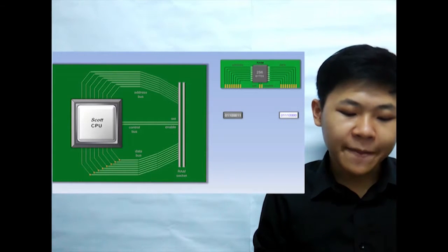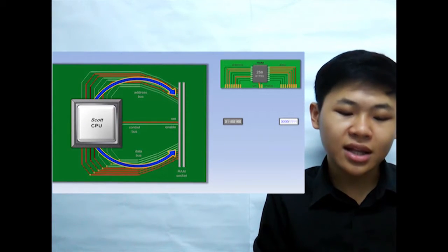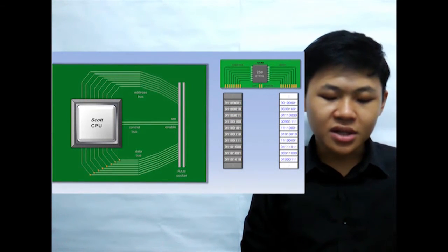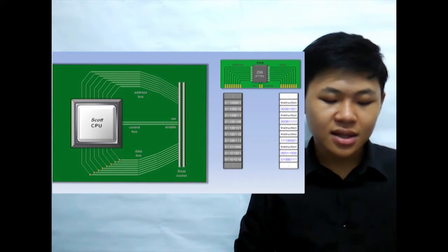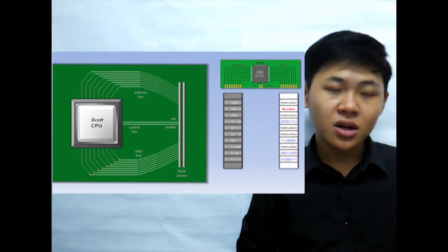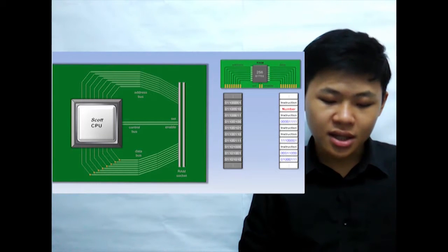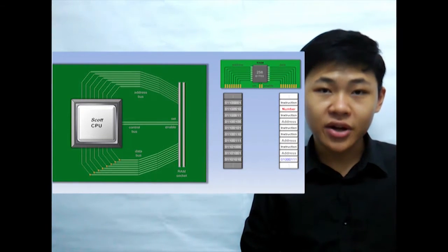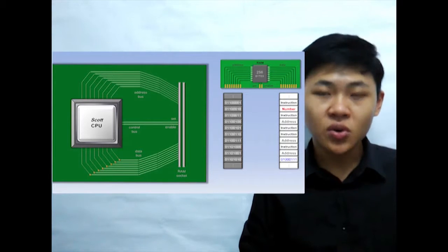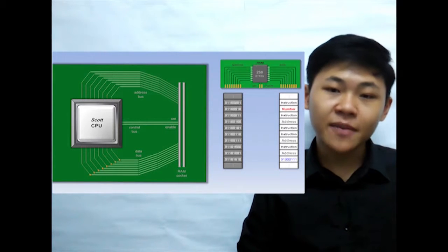If the CPU wants to send data to the RAM, it will output an address, then output some data, and then turn on the set wire. The RAM will then overwrite the data at the address with the new data. Although the data in RAM just looks like bunches of 1s and 0s, some of it represents instructions which tell the CPU what to do, and also numbers which are used to add, compare, or simply process somewhere. Another thing is addresses. A particular memory address in the RAM can itself be data. For example, this address is used to output a number to an external device, and it has to know the particular address of the device. There are also letters in RAM, represented by character codes.